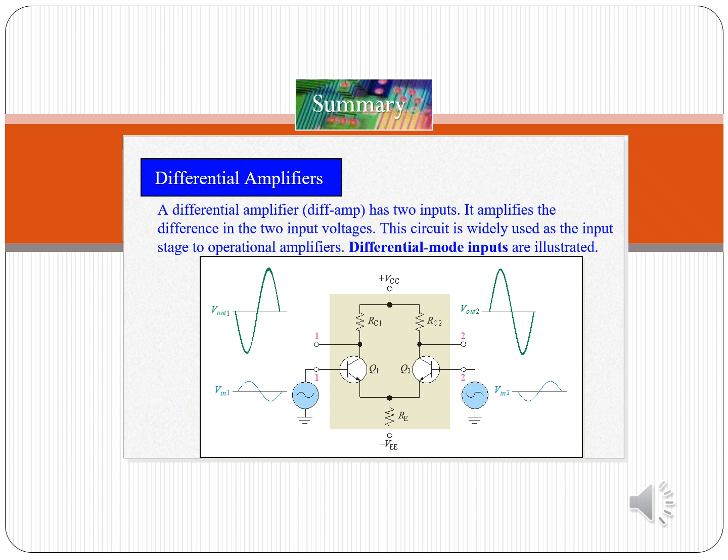So this circuit uses two transistors, typically matched, and it has two inputs. Instead of amplifying a single voltage, it amplifies the difference between two input voltages or two input signals. And that's what makes it differential. And why does this matter? Only the difference between V input 1 and V input 2 gets amplified.